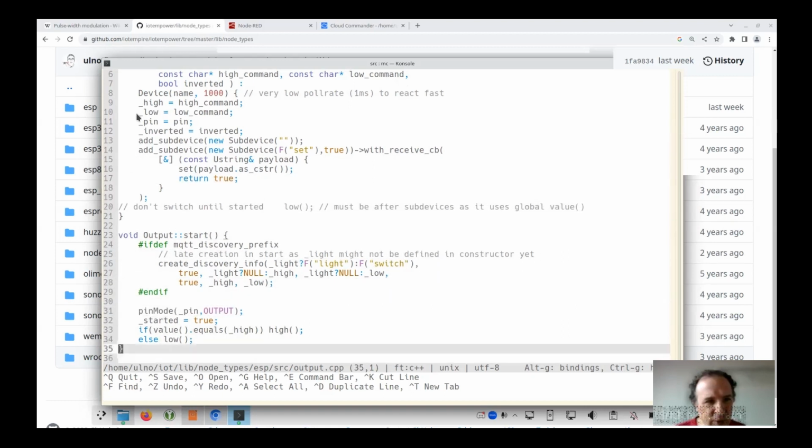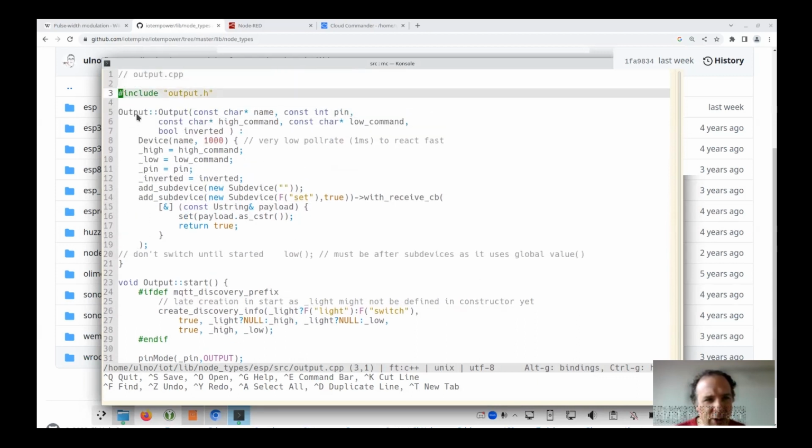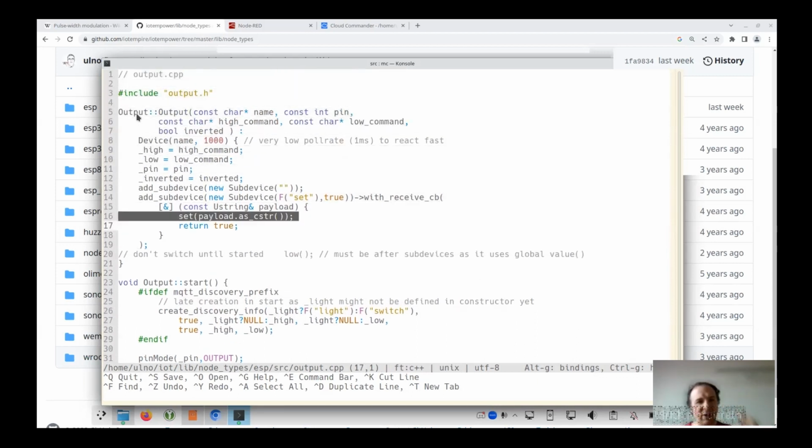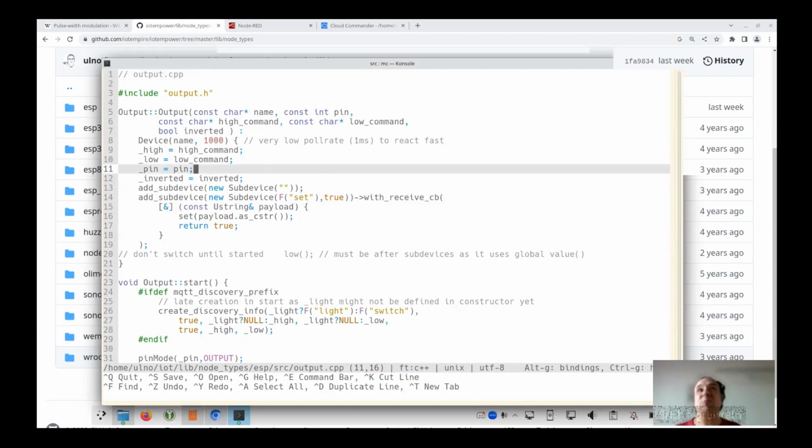And here you see a closure in C. You see basically that this calls a set function based on the payload you get. So what are these files for? These are the drivers that make it work. These are the wrappers around the classic Arduino code that allow you to have just one command per file. So this is trying to take all the work away from you to make this accessible.